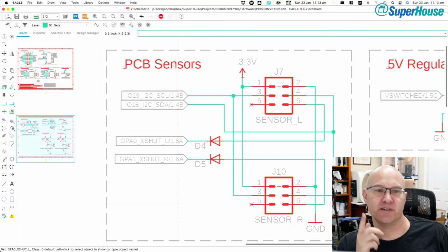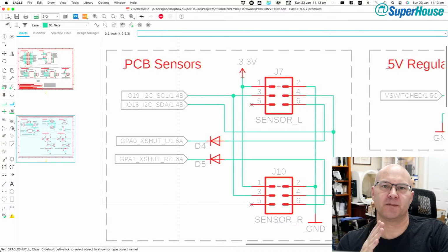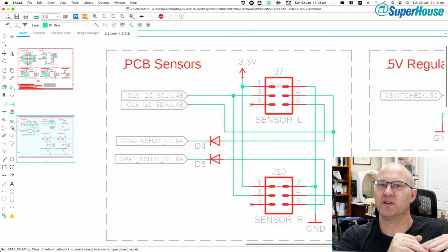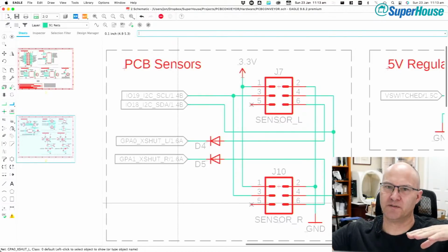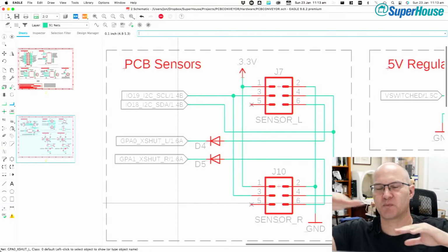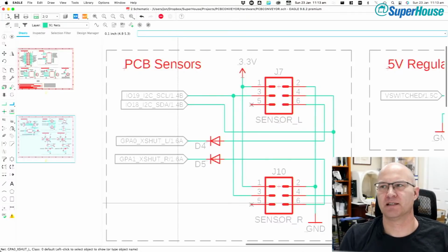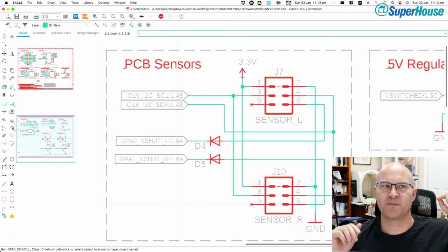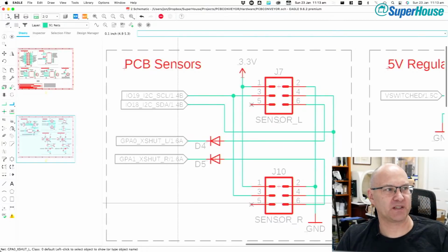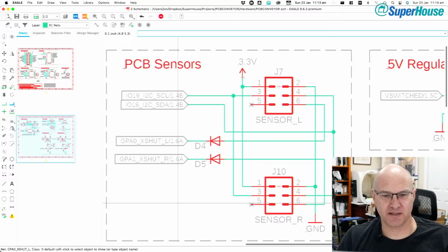So Austin, that is a very, very good point, because the thing is that we actually only care about those sensors if we are in the process of, say, loading something onto the conveyor belt or offloading it, and we want to detect the fact that it has passed the exit sensor. So what the logic can do is shut down all of the proximity sensors unless the conveyor belt is in motion. And I think that's probably a good way of extending the life of those little time of flight sensors.